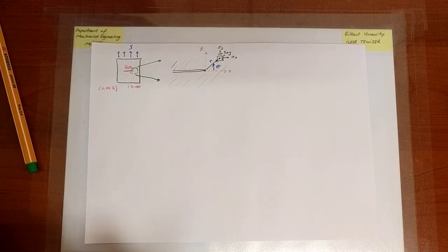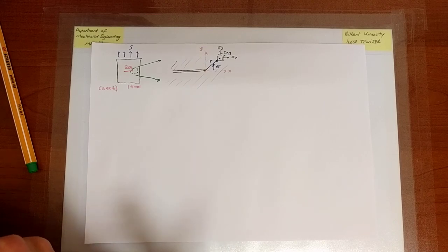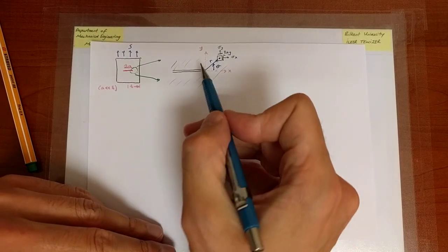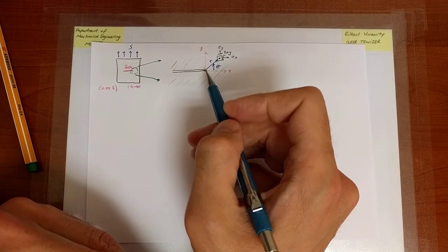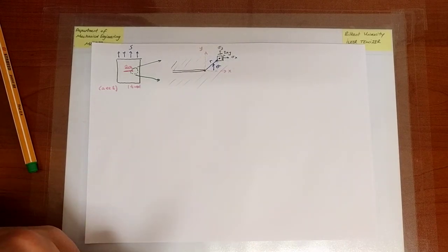That is why we call this topic linear elastic fracture mechanics, because we are basing our tools of fracture analysis ultimately on an analysis that is realized through the assumption of elasticity. Now, is that reasonable? It's not. To a large extent, actually, it's not, because we know that the stress field at the tip of the crack is so large in the y direction that no material can actually sustain it.